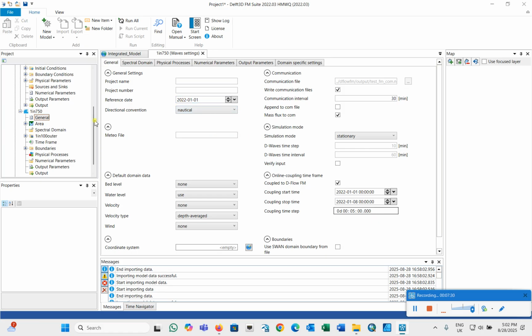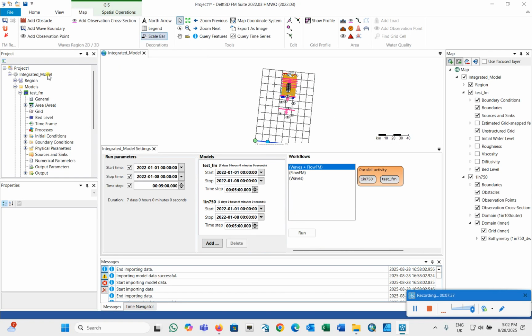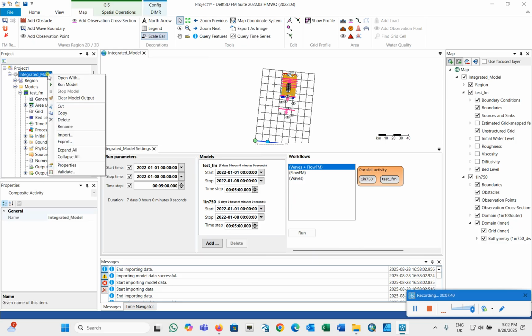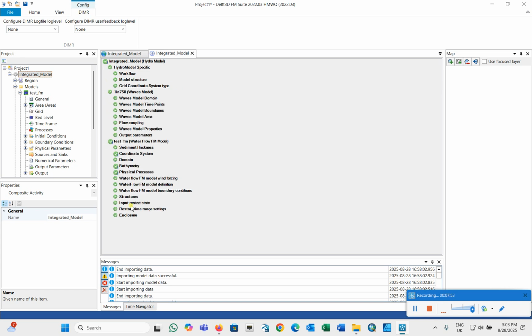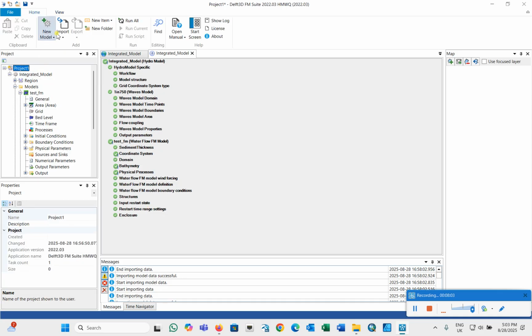So after this setup, the model is ready to run, but let us check if it's really ready to run. Because I already have that model setup done, I'm just gonna validate this. And when you validate this, you'll probably see all of the green. You want to see all the ticks are green, because it means that everything is okay and it's good to go. And you can see all the parameters are in line with the setup file that is required. And then after that, if you just click run, then the model should start running.